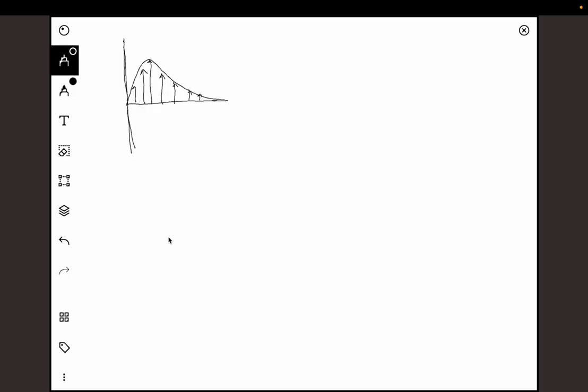So let's say this is the peak velocity, Vmax. Instead of natural convection, let's say this is TW, which is constant, and this is T infinite. What we can do alternately is take the same plate with the same temperature, but instead of natural convection, what if we had forced convection, wherein you will have a constant velocity, so that you will have the boundary layer something like this. And the velocity field is Vmax. I mean, the free stream velocity is equal to Vmax.